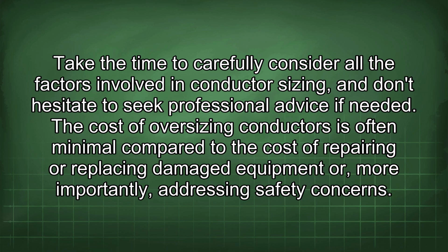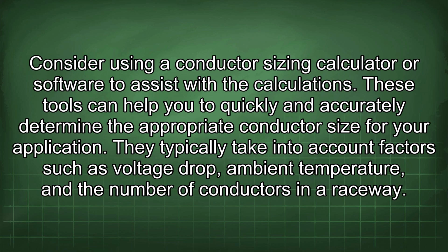The cost of oversizing conductors is often minimal compared to the cost of repairing or replacing damaged equipment or, more importantly, addressing safety concerns. Consider using a conductor sizing calculator or software to assist with the calculations. These tools can help you to quickly and accurately determine the appropriate conductor size for your application. They typically take into account factors such as voltage drop, ambient temperature, and the number of conductors in a raceway.